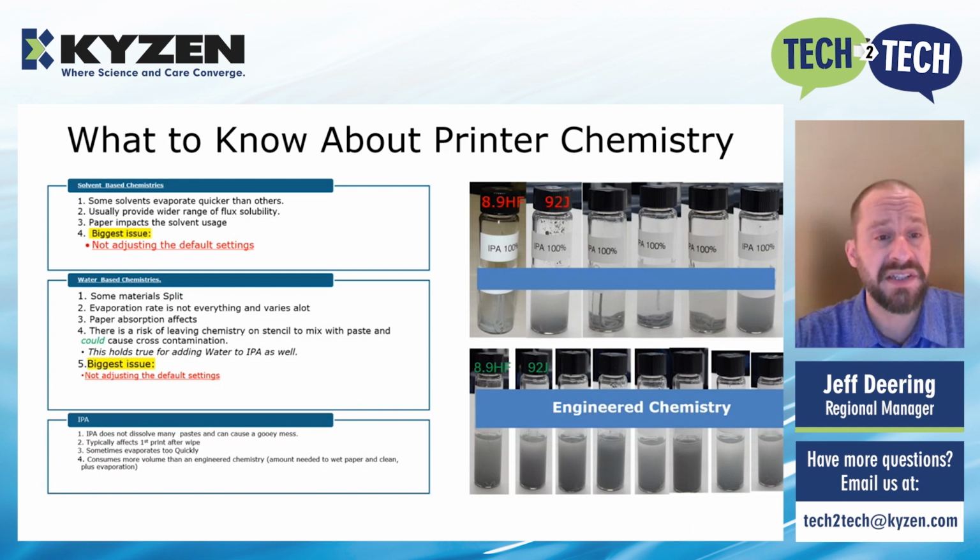Now moving into water-based chemistries. Some materials split. The evaporation is not everything and can vary a lot. Again, the paper absorption rate affects the usage of the water-based chemistries. There's also a risk of leaving the chemistry on the stencil, which can mix with the paste and could cause cross-contamination. This also holds true when you add water to IPA. Again, the biggest issue with water-based chemistries is not adjusting the default settings.